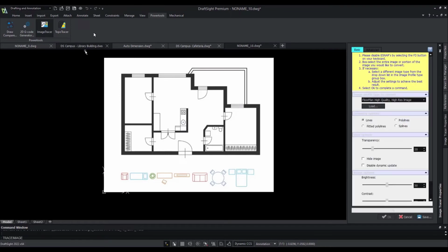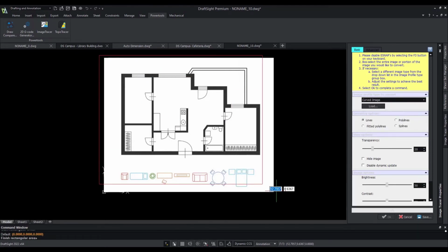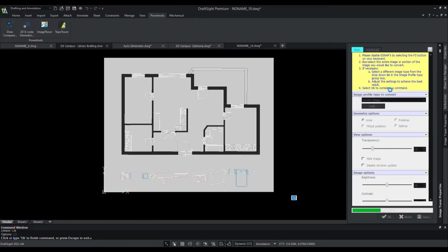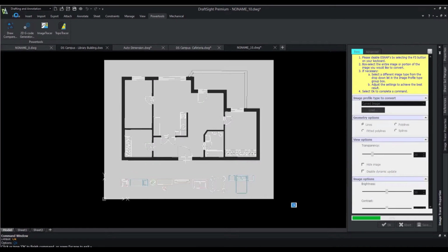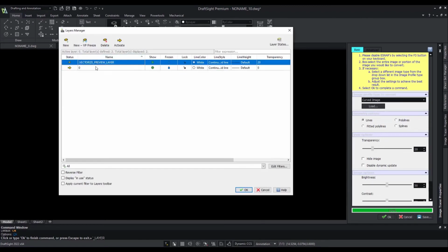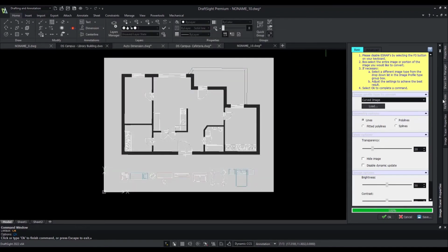The images can be architectural plans, floor plans, logos, and curved images. The tool generates lines, arcs, polylines, and curves from the vectorized image and places these objects into the active DraftSight layer. We can use the objects as a resource in our drawing.